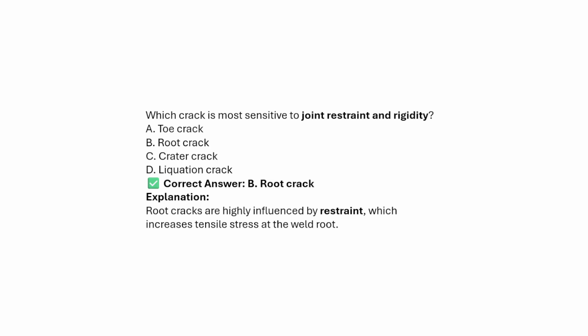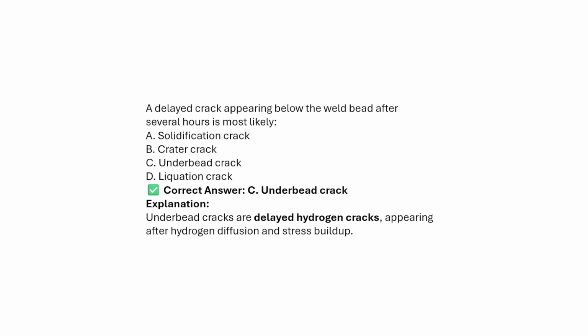If we put in restraints, the deflections are suppressed. If the deflections are suppressed, more stress concentration will be generated, at the center region at the bottom, and that will be the root crack.